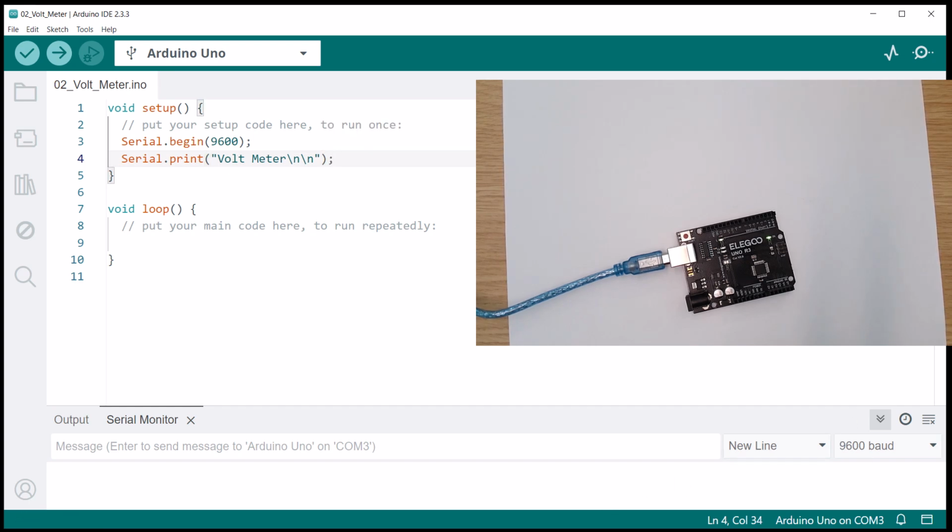Now I'm going to come down here and use the following function: analogRead. I'm going to write this in little pieces so that we can construct it together. analogRead is the function, and I open it up and give it either the input pin number, or I can use descriptive names like A0.